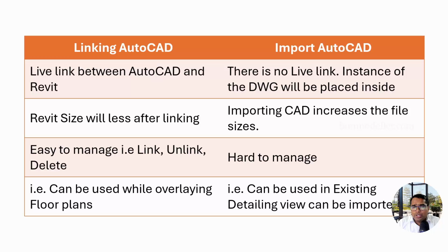But after importing also, you make sure that you have the right line type matching with the Revit. That is more important. In my case I would suggest this, because imported files will have n number of line types, n number of object styles and hatch patterns, which leads again to more file size. You import it and you have to audit it yourself and make sure that it is used with the right line type, and other graphics as well. So make sure that you do that.